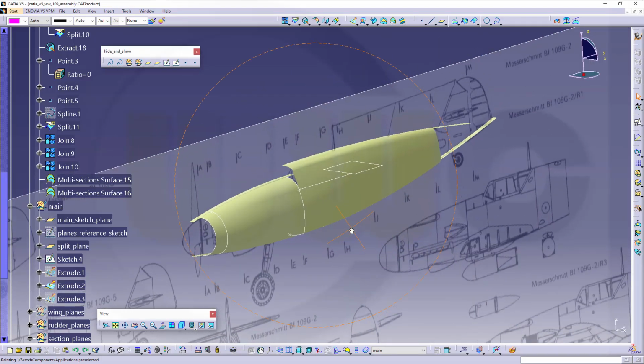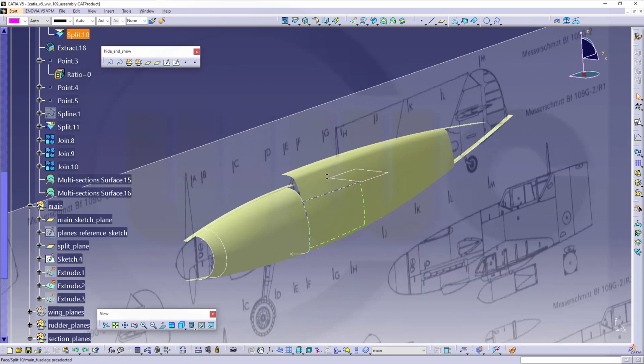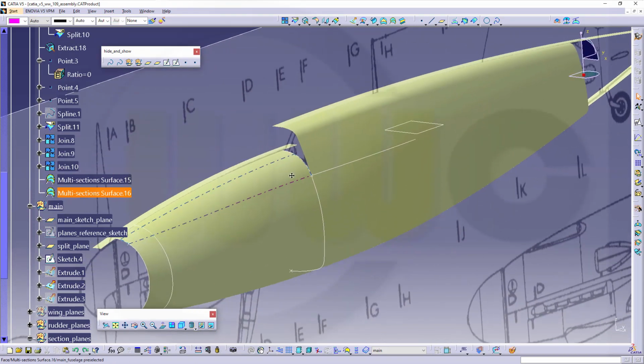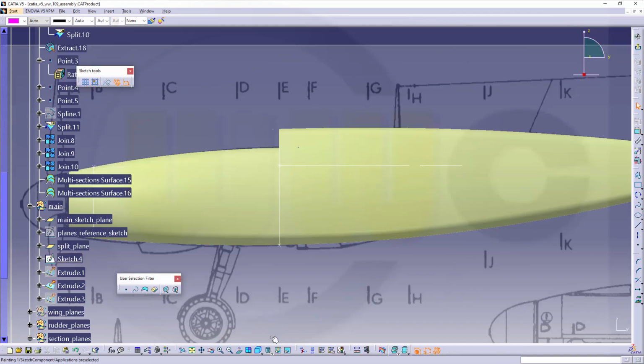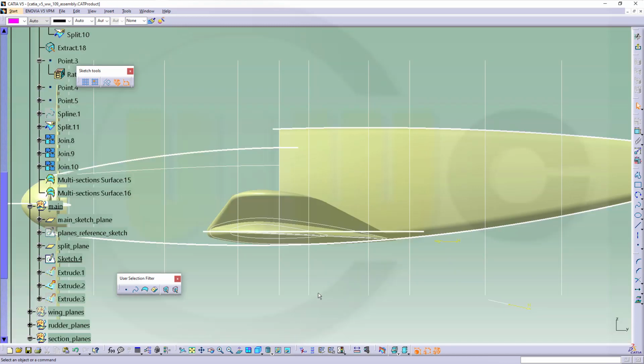Now in order to get my cockpit cut, I want to make here a surface. Therefore it would be very helpful if this one would be longer. So I want to change that length here. How to do that? I will go to sketch 4 and go to the invisible space, and I want to lengthen that curve. So I should go for trim, select that curve and just make it a little bit longer, maybe up to this. Okay.